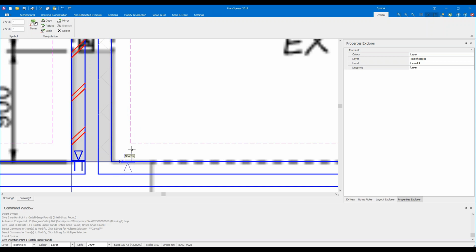So we'll place this one on the internal leaf of the same part of the wall. Again, we're going to click first on the right hand side of that internal leaf. We'll find the end point there, or whatever snap point you find. So that's positioning the wall starter.